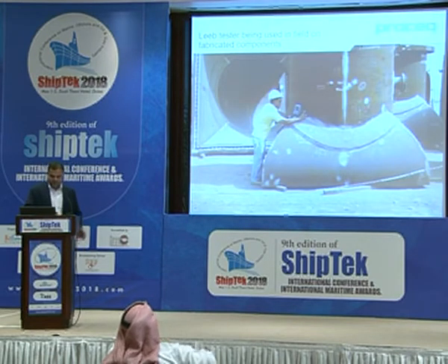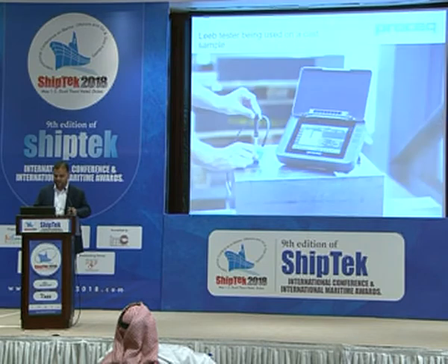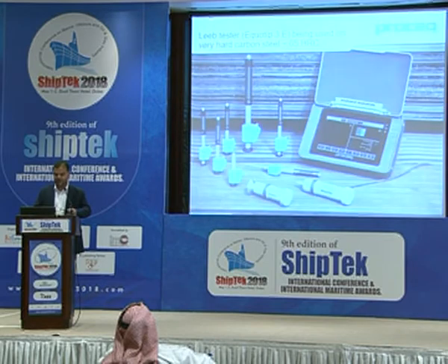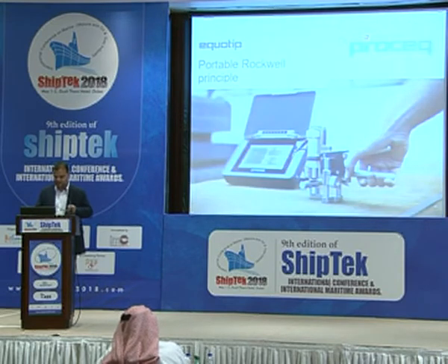Some interesting applications used in the field of fabricated components here. This was in Hamriya free zone, and a Leap tester being used on a cast sample. An ideal application for heavy and large components. So it's being used on very high hardened carbon material.